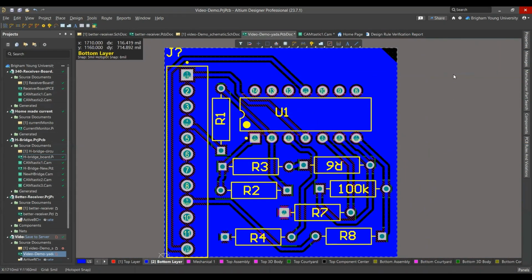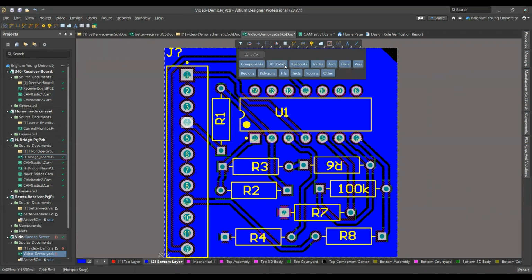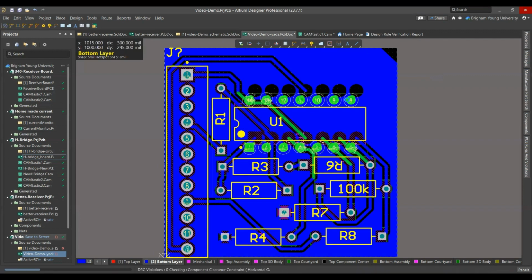If you managed to keep track of everything I did, I tried to auto route and it didn't work at first, so I had to move a few components around, and then I re-auto routed it so that it would work nicely. Other tricks that I've learned is if you click on a trace and then you shift click, it will show you the whole trace so you can follow a path along. This will be helpful when you're later trying to debug your circuit, because you can see where your traces lead to, or if you just hold shift. The filter tool is very useful to select components, or if you just wanted to select the polygon or not click the polygon, you can unselect it, and now you won't select the polygon, but you can move everything else.